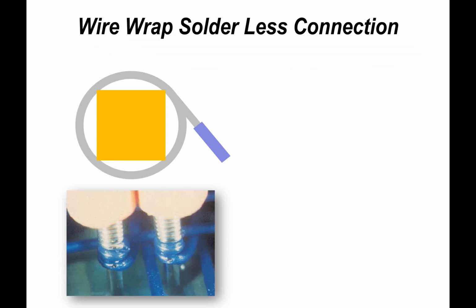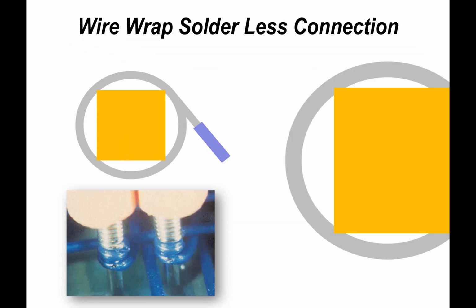Now, when my company went to telecom products, we were in competition with 3 major companies in the UK, all producing for the telecom market. It was a vast market. And all of those 3 companies were basically producing backplane products for interconnection, and all of them were using wire wrap. Wire wrap is a method of producing an electrical connection with no solder joint, but a low resistance. So there would be no resistance change on this interconnection method, even though we weren't soldering points of wire to terminations. Basically this process worked by wrapping wires around a square pin.